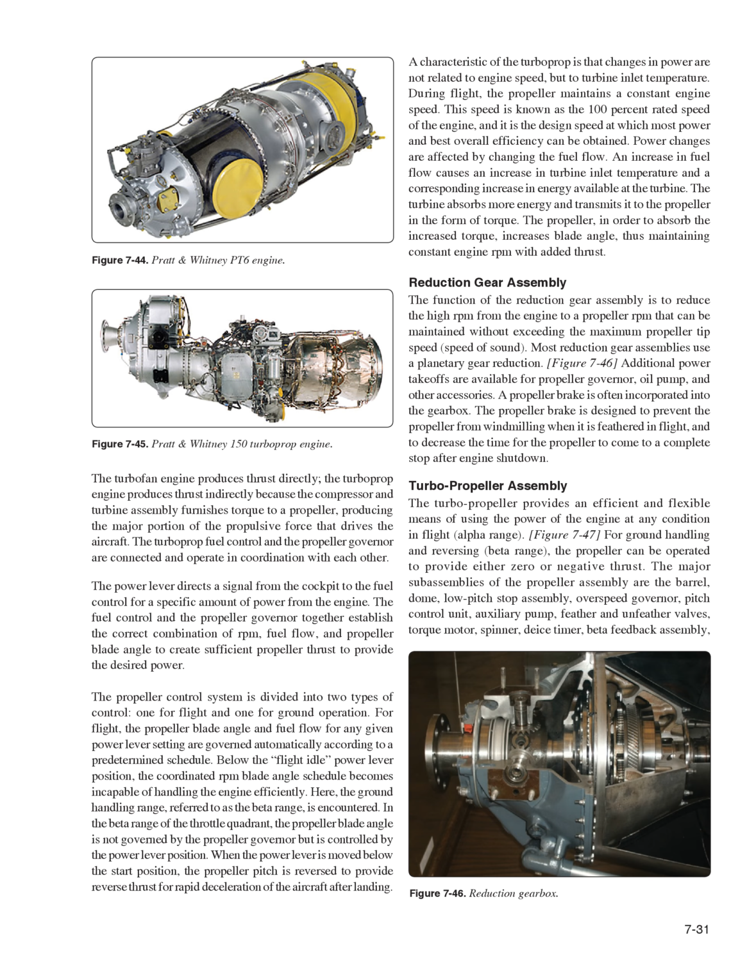A propeller brake is often incorporated into the gearbox. The propeller brake is designed to prevent the propeller from windmilling when it is feathered in flight, and to decrease the time for the propeller to come to a complete stop after engine shutdown.